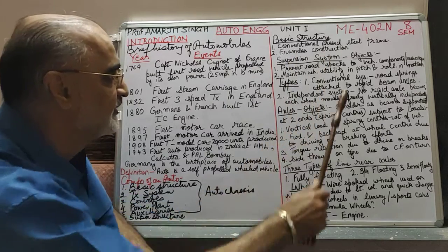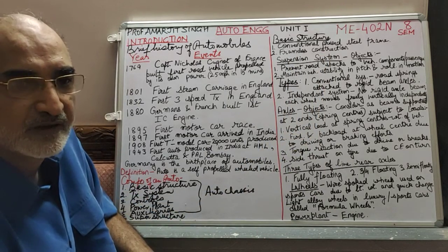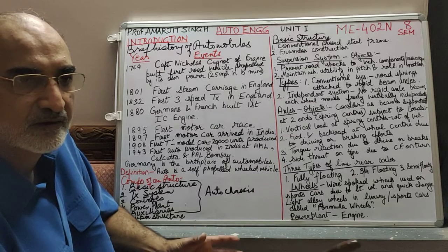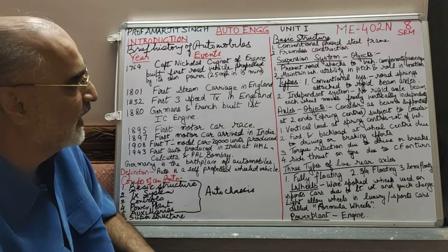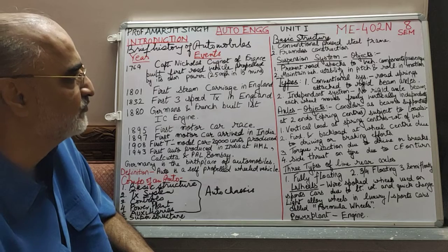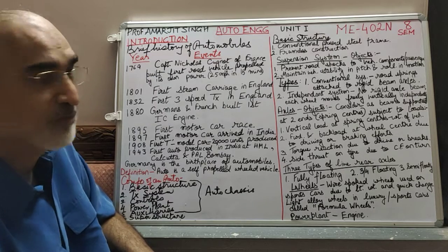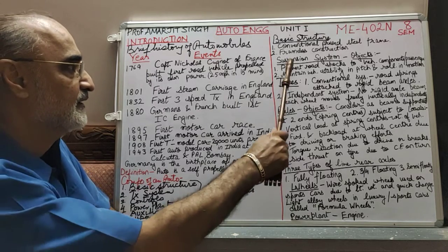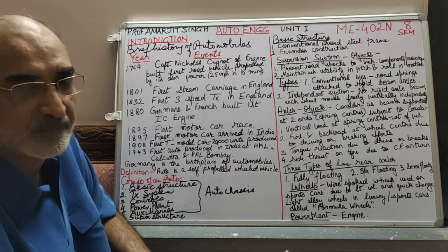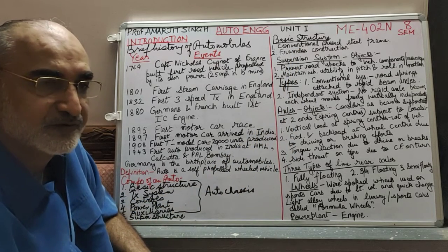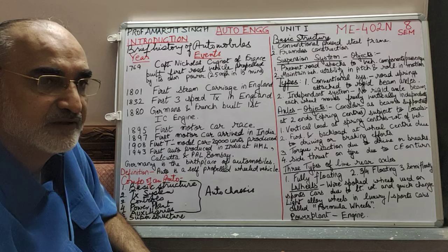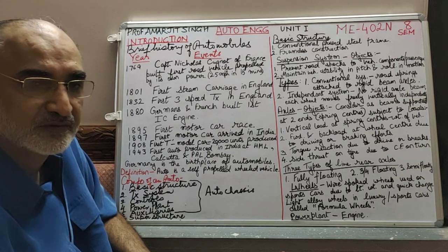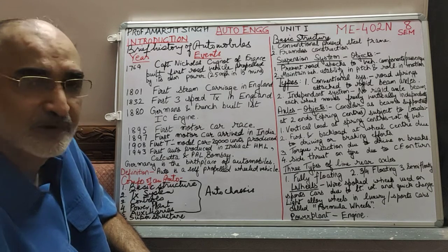In frameless construction, there is no frame. It's like an enclosed body, and since there's no frame, all the forces which come on a vehicle will be on this construction. That means even the pillars, the windscreen, the side doors and the other parts will all be load bearing.